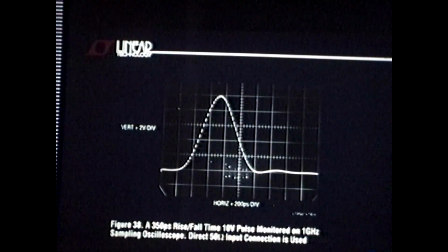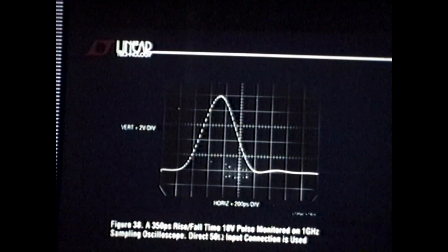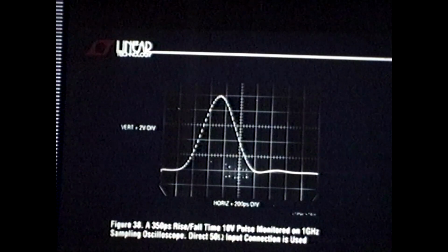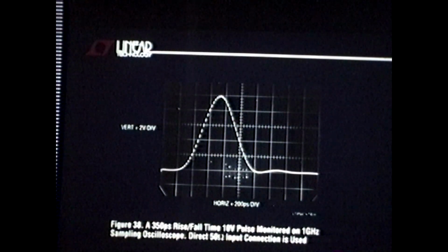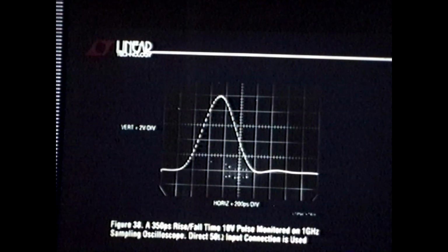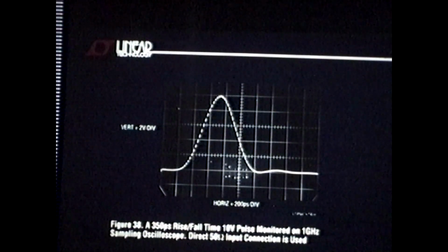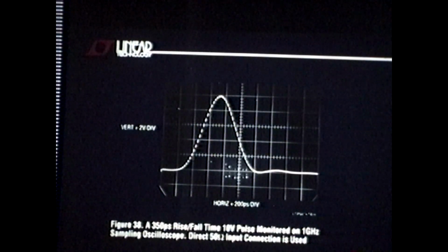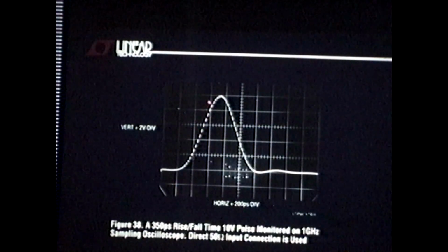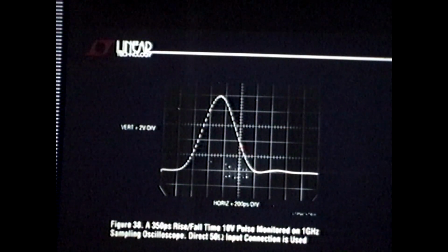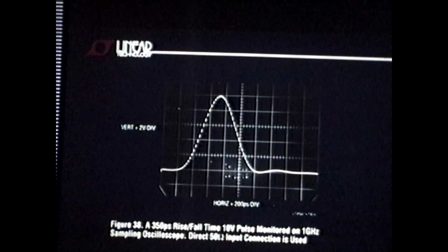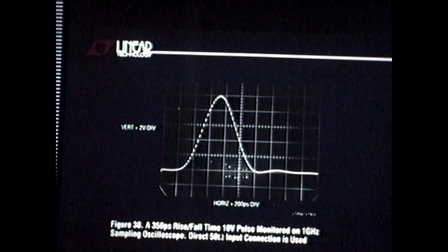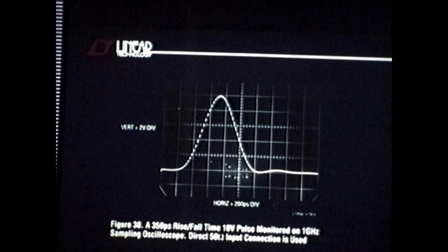Remember, in various circuits and for various waveforms, I tell you, when you see rounding and symmetry in waveforms at speed, it's not necessarily the case, but it's likely that something's bandwidth limiting. Look at that waveform. I'm beating my chest that this is taken on a 1 gigahertz sampling scope. But never mind the number. Williams says, when things look too symmetrical and too clean at speed, the thing may be bandwidth limiting. Well, the problem is 1 gigahertz is the fastest oscilloscope I've got in my house. So what does the thing really look like?